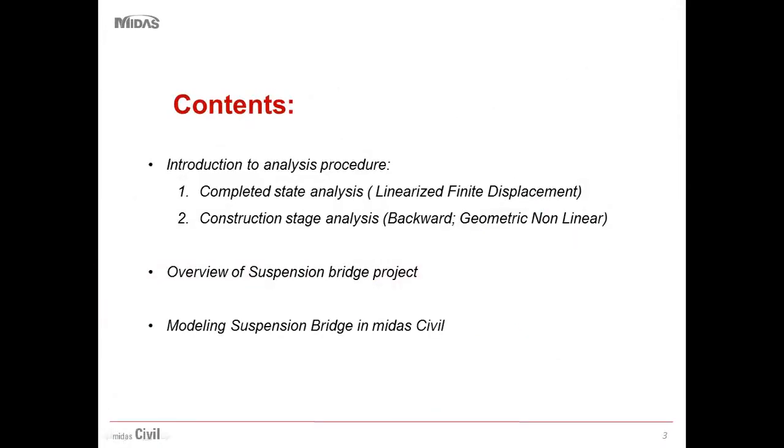These are the contents of our webinar today. We'll first talk about the different analysis procedures required for a suspension bridge analysis. First, completed state analysis, which is also called the linearized finite displacement method. Then construction stage analysis, which will be backward and will include geometric nonlinearity.